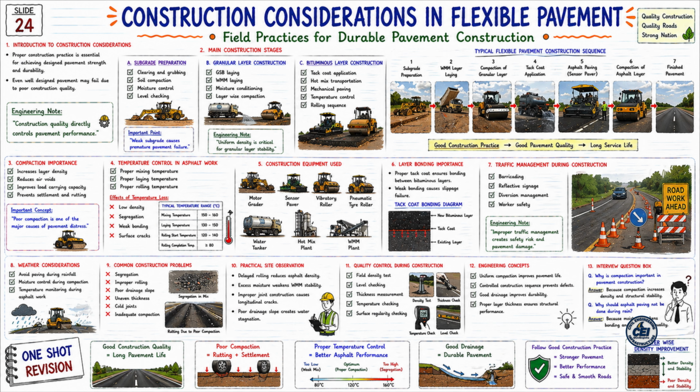Traffic management during construction. Traffic management is also very important during construction. Barricading. Reflective signage. Diversion management. Worker safety. See the engineering note below. Improper traffic management creates safety risk and pavement damage. And this is very critical for highway safety. Now let us look at the 8th topic.